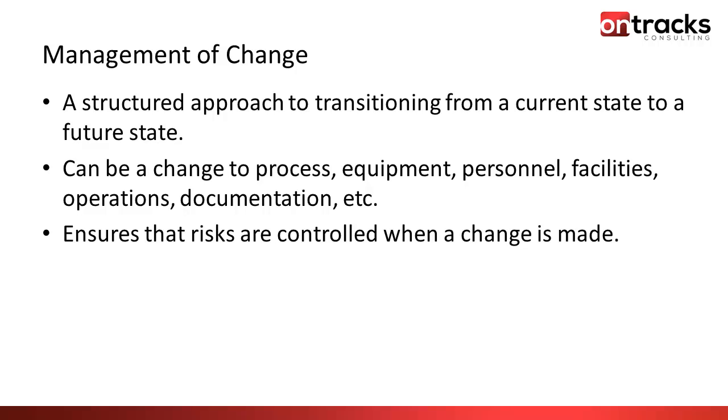So a typical MOC procedure should include a number of things. It should include key MOC steps, so that would essentially be your process from beginning to end. It should include a definition of what a change is and what a replacement in kind is. A replacement in kind would essentially be replacing something, whether that's equipment or a procedure or something like that, with something that is very similar.